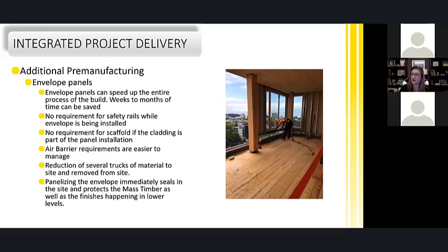In the future, so in Brock Commons, we didn't have balconies. We have balconies on our other projects, and we do those as a clip-on to the building. So we found different clipping solutions where we can clip them into the building using the crane, and then that becomes basically a safe zone, and the railings are all integrated as part of that, so it just basically locks on and they keep going. It is a tricky detail. I can't say that it didn't take us a long time to solve it. It took us months to figure it out with lots of very creative people, but it isn't impossible to do it.